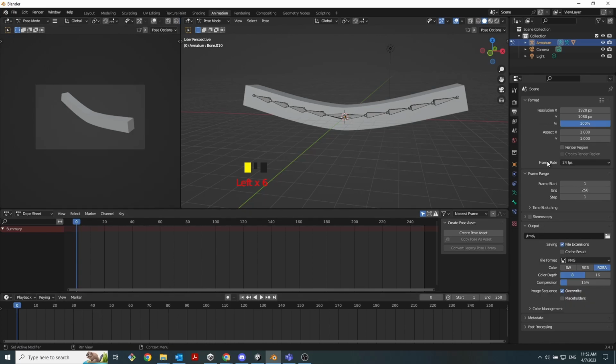So usually a frame rate of 24 per second of the video is good. If you are at 24 frames per second, then in a second you have 24 frames. So decide how long your animation would be. You want the beam to deflect in 2 seconds or 3 seconds. Let's say in this one we want it to happen in 3 seconds, right? Then you can click and drag this timeline, go to 72 frames, that is 3 seconds.